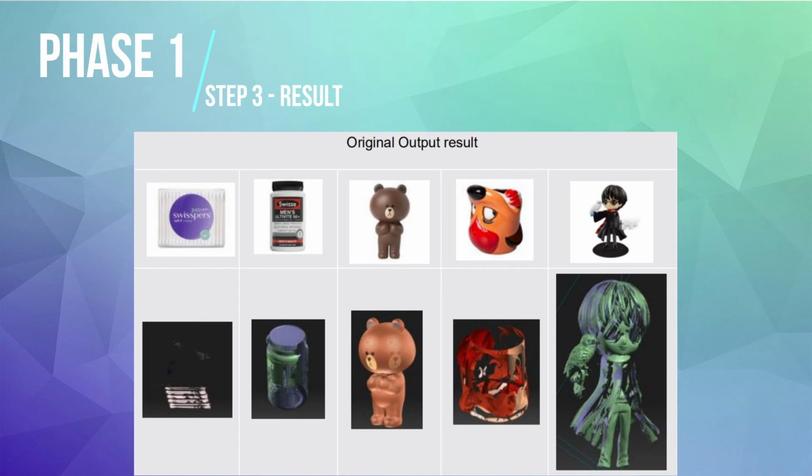The black object, whether with a matte surface or a smooth surface, will absorb some light, and the information cannot be transmitted to the camera, resulting in the missing part of the scanning image. For objects with a high reflectivity and smooth surface, the light from the projector will scatter when it reaches the surface, which means that it may reflect in another direction rather than back to the camera, resulting in part of the image not appearing in the scanning result.